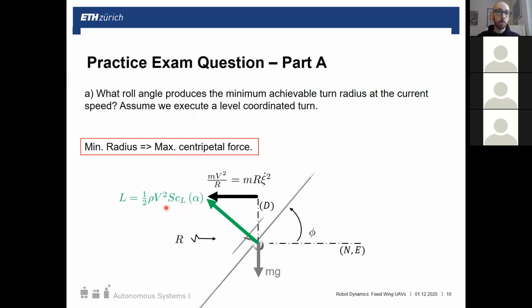Here we only considered angle of attack as a way to change the lift coefficient for a given airfoil, but you can also change the lift coefficient with deflection of flaps. Further, the elongation increases our surface area, so we again get a bump in lift. Okay, I really have to catch up on these questions.